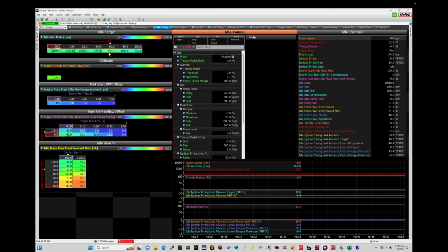So it takes a little bit of time for us to move either the idle stepper motor, idle control motor, or the throttle blade with drive-by-wire to get the desired idle result that we're after, to try to get the engine's torque output regulated to run at that desired idle speed. So we have our slow path control, which is airflow based, and our fast path control, which is going to be spark timing based. Now we can virtually command the spark timing to do whatever we'd like and do it almost instantly in our programming. And the spark timing movement, let's say 10 degrees of movement, which can be commanded in microseconds within the programming here, can have an immediate effect on the engine's torque output.